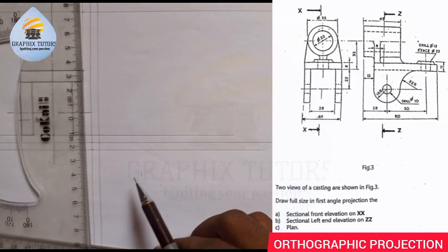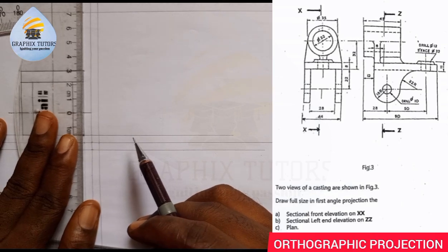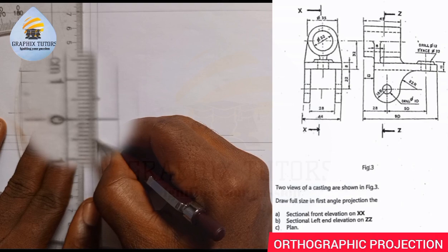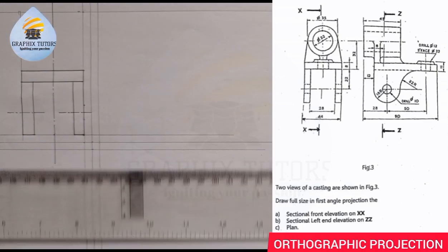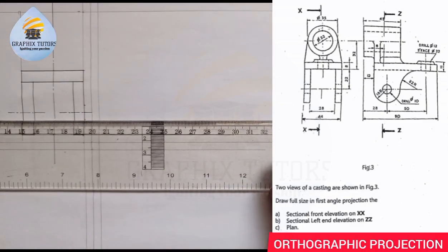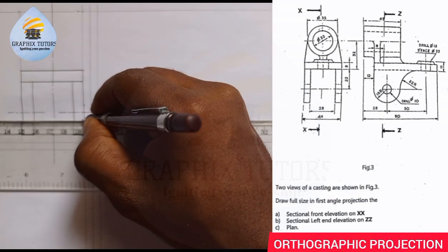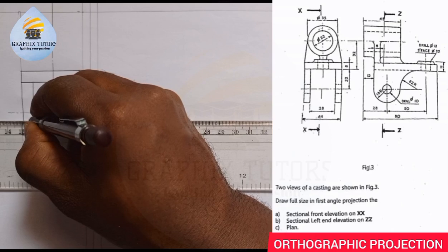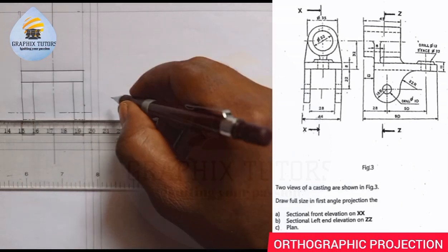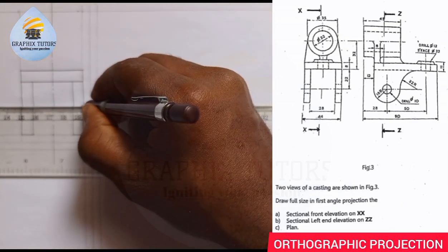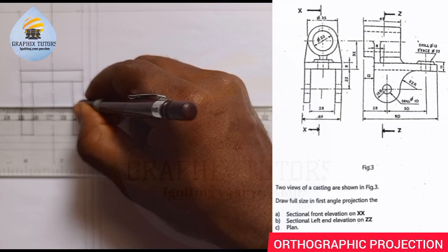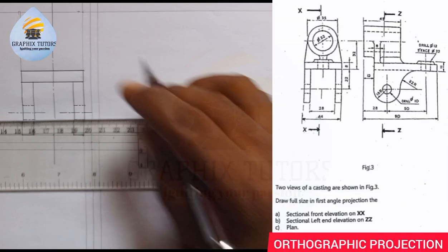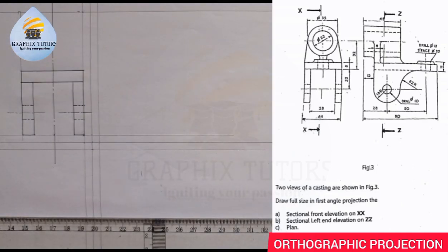So from here, after placing it here this way, I measure 5 upward and 5 downward, so making 10. That is where I'm going to draw my hidden line. So when I do that, this will be hidden, hidden, hidden, hidden, hidden, hidden, right? I'll come here also, I'll do the same thing. You just use short lines to represent your hidden line. You can see that? So that is for that one there.